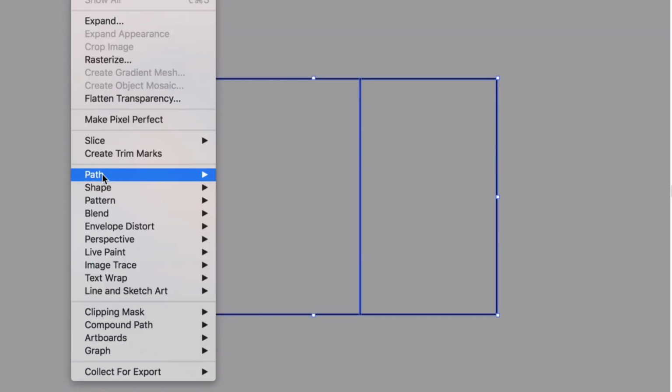So now what we're going to do is we're going to rotate this, and we're going to put the same ratio on the right side. And so we're going to continue to do this over and over until we get what I've shown you before, what it's supposed to look like. So we're going to take this. I went ahead and went to Path and outlined the strokes, so when we make it smaller, the stroke sizes are not going to change.